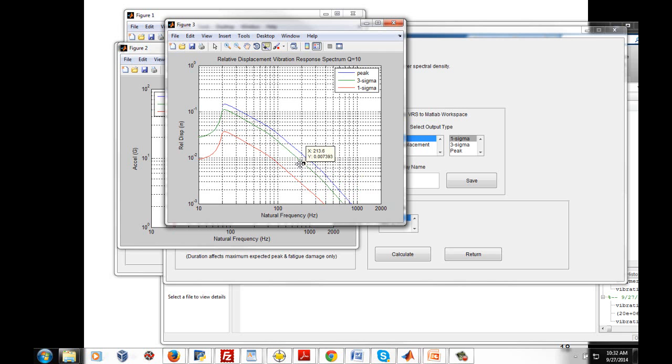On the other hand, if we go downward in natural frequency, it looks like we cross the threshold at about 175 hertz. So at 175 hertz, the failure would occur close to 20 million stress reversal cycles. But then if we take our natural frequency even lower, you can see that we're just in worse shape yet, and failure occurs before 20 million stress reversal cycles.